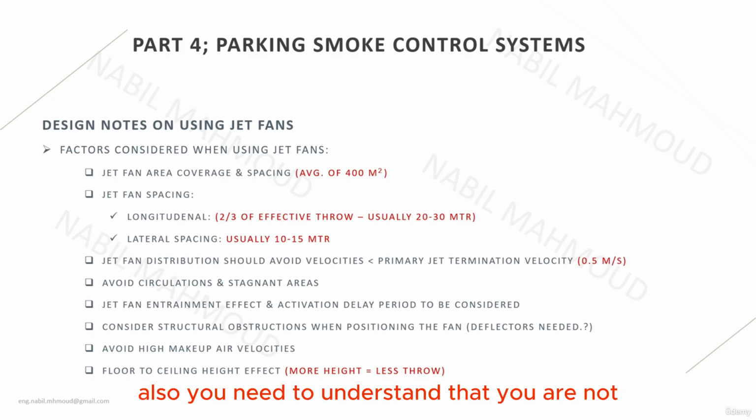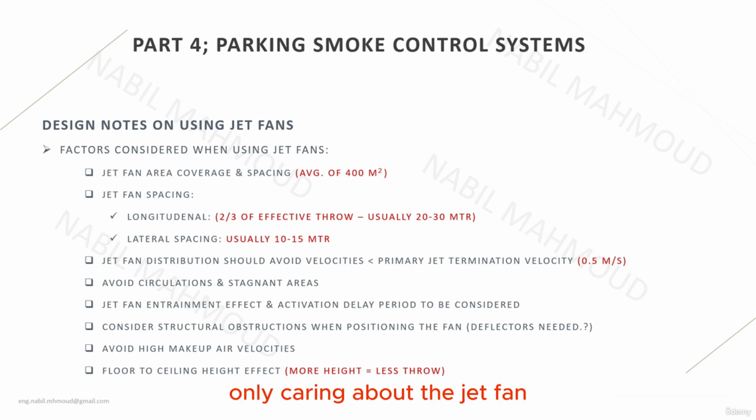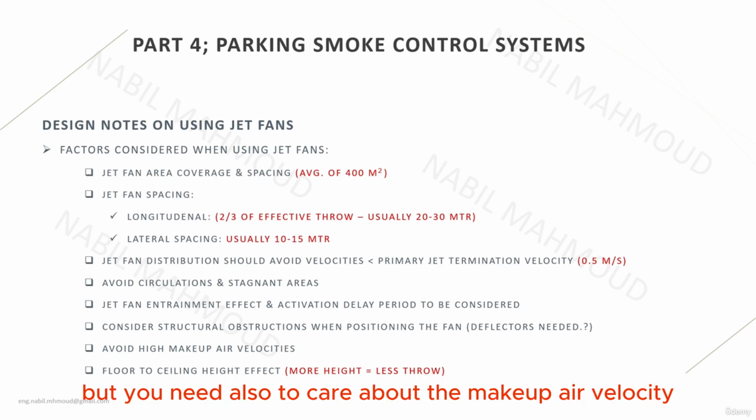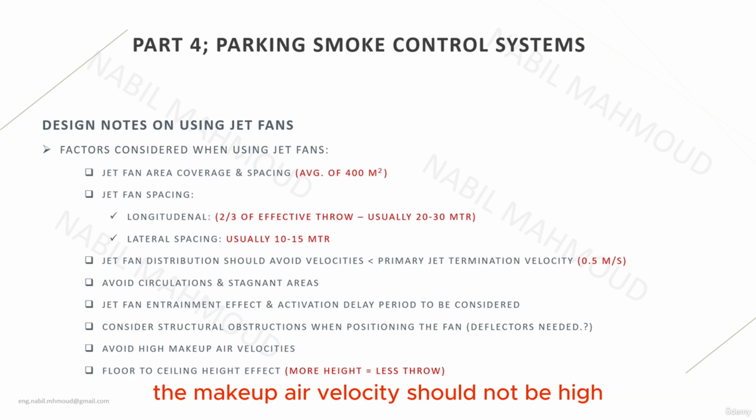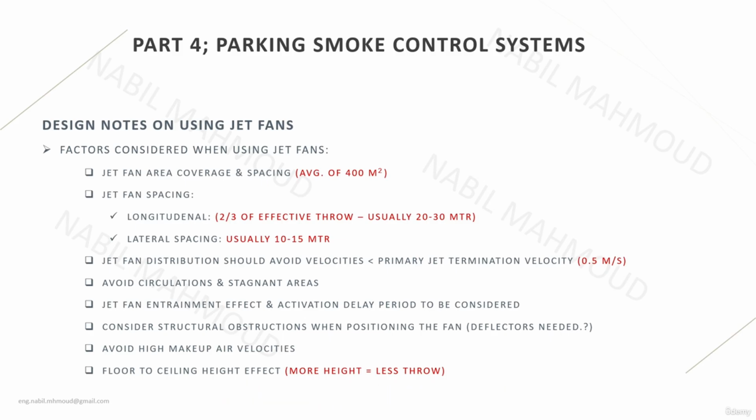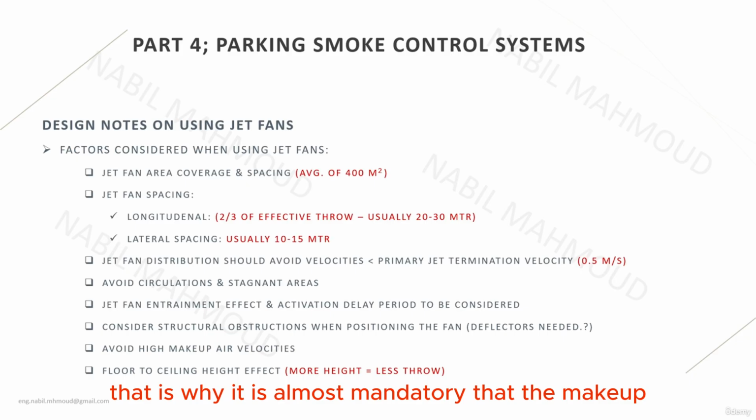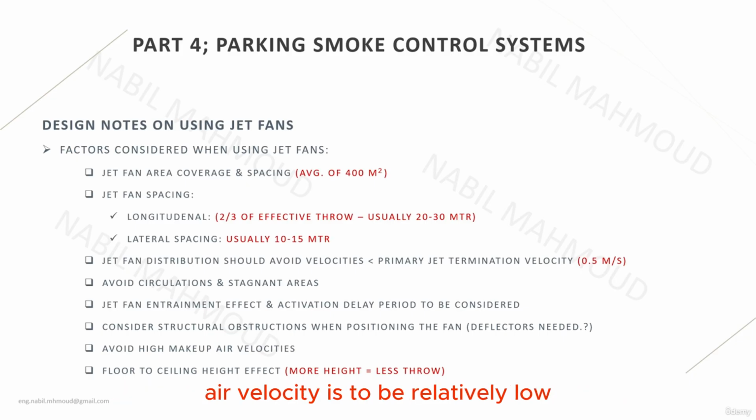Also, you need to understand that you are not only caring about the jet fan inside the area. Let's say this is the parking, you're not caring only about the jet fan and the exhaust fans, but you need also to care about the makeup air velocity. The makeup air velocity should not be high, because if it is high, it will cause circulations, and these circulations will act like mixers. They will mix the fresh air with the smoke or pollutants. That is why it is almost mandatory that the makeup air velocities be relatively low, in order to maintain a free, fresh stream of makeup air without any circulations or mixing of the pollutants or smoke